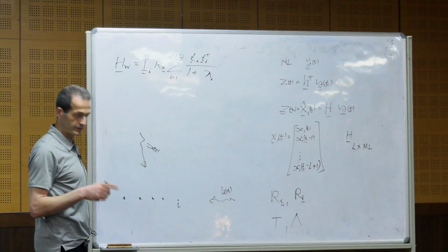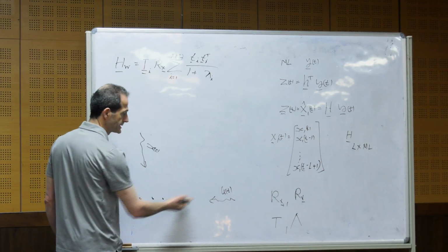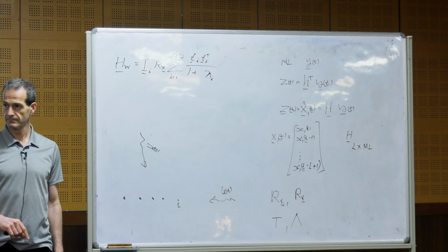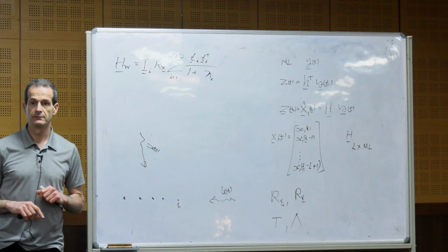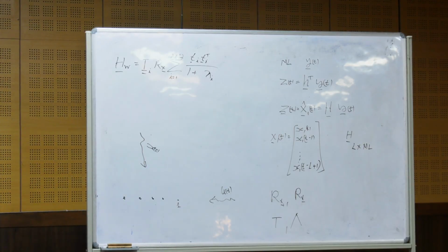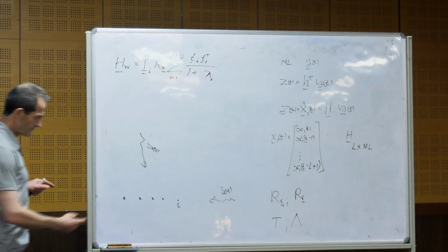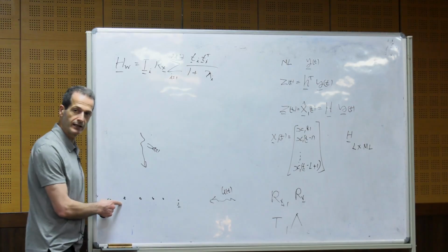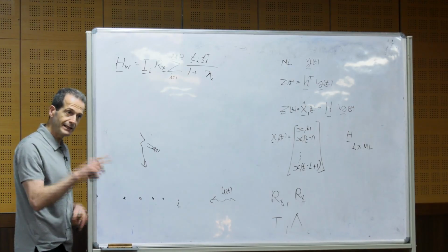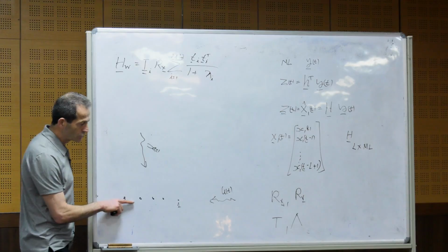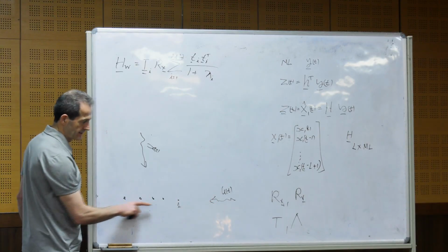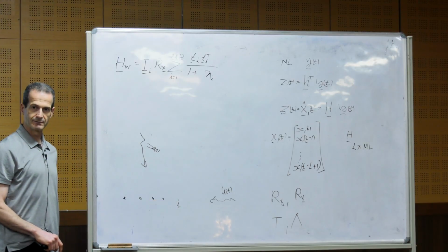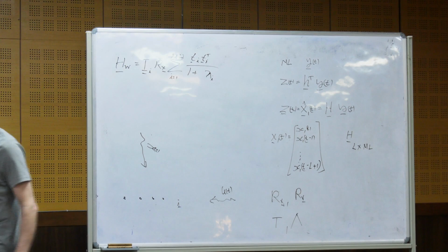We talked about the beam pattern. So I want a beam pattern such that a signal that comes from this direction will be suppressed as much as possible. The filtering matrix takes into account the correlation between samples here and samples in any of the sensors, and based on these correlations, tries to minimize the amount of signal that is measured from this direction. Okay? This is what we're trying to do.